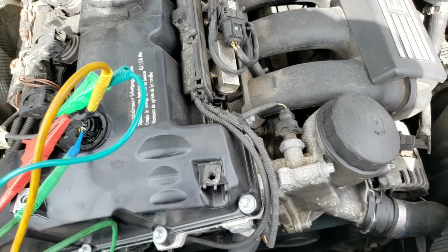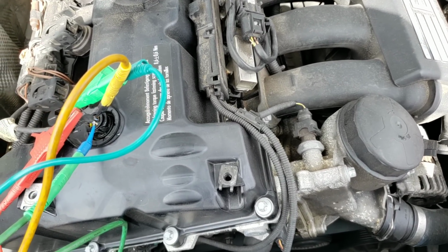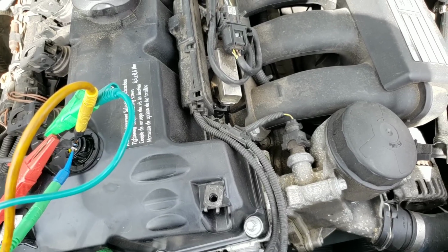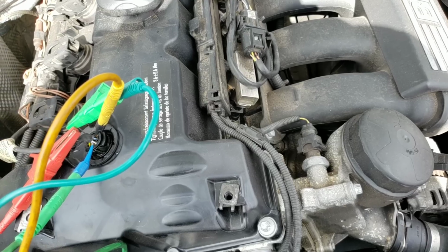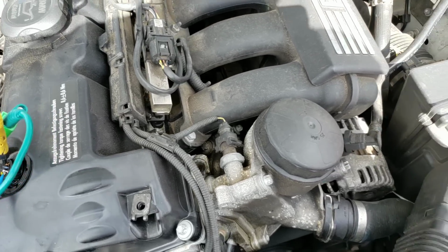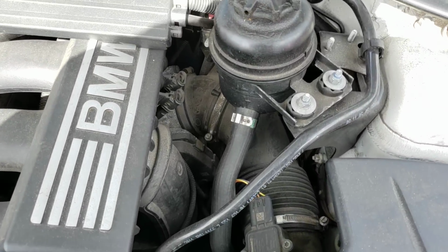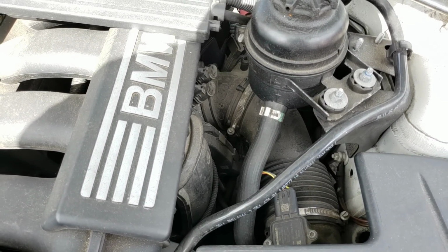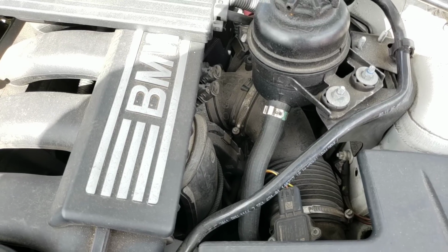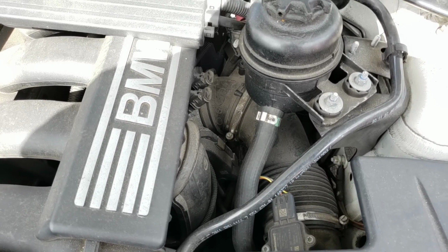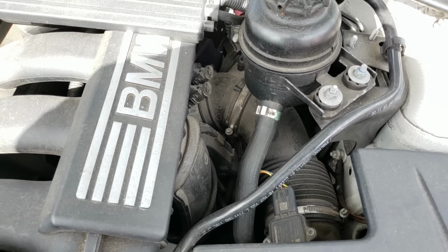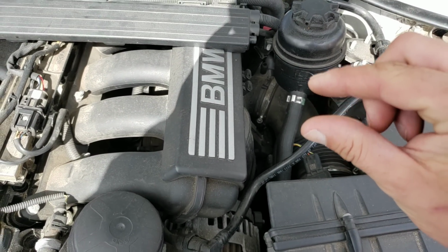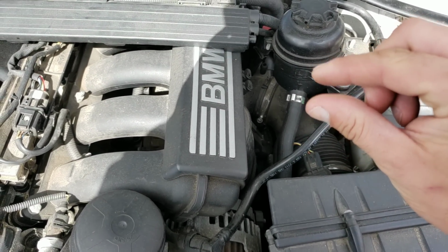Unless there's a huge fault, something that has to do with the Valvetronic system, and at that point the throttle body will close. The Valvetronic is a variable valve lift. So when we have our engine sitting here at idle, the only time that we actually need to control the amount of air going into a cylinder, or the only time that we really need anything at all for what we can call vacuum or a slightly lower pressure, would be when we open up the valves. And depending upon how much we open up the valves, we have a minimum valve lift, we have a maximum valve lift, and that's what Valvetronic is adjusting.